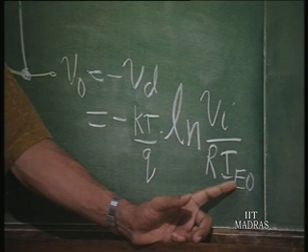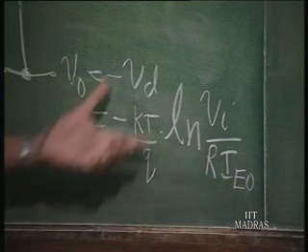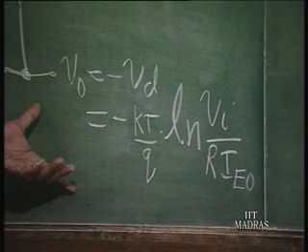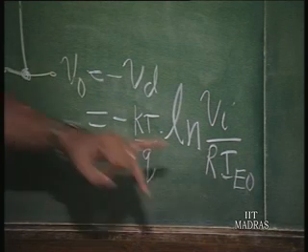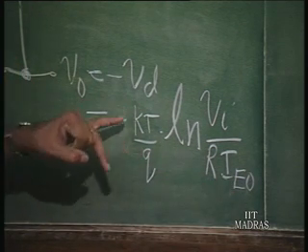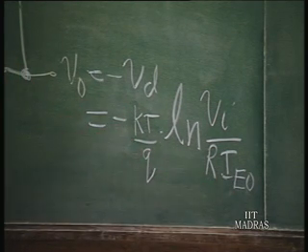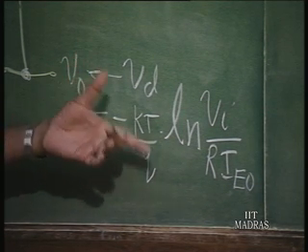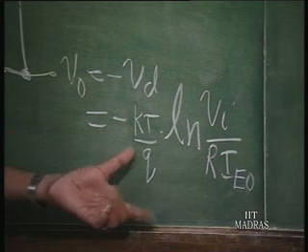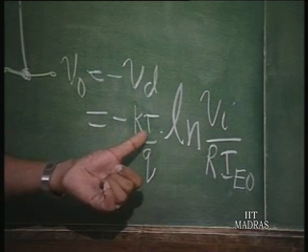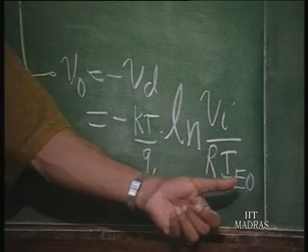This doubles for every 10 degree rise in temperature. So, this is no use as an amplifier if I do not compensate for this variation as well as this variation. So, if I want to use this as a compander, or use it as a log amplifier, I have to compensate for temperature variation here as well as here.